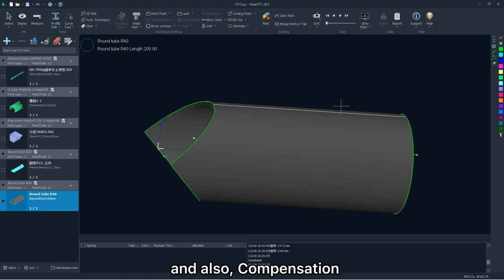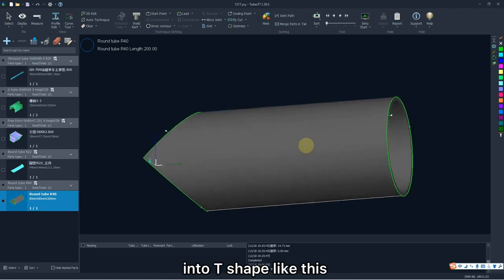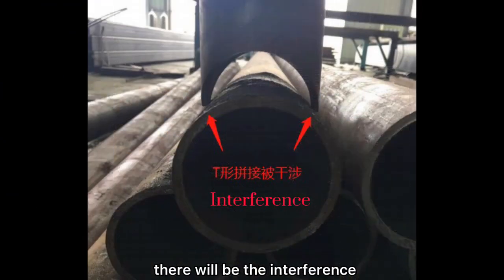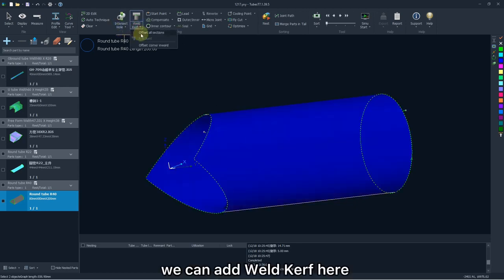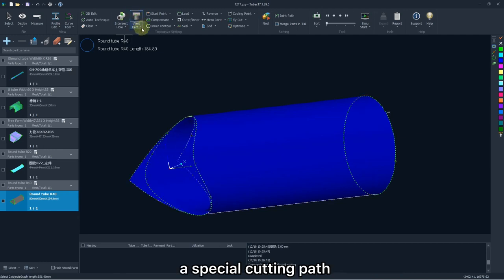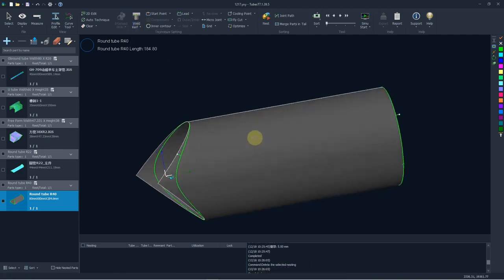And also compensation for special parts to be jointed into a T-shape like this. If you just cut it according to this kind of cutting path, there will be interference due to the differences between the inner and outer control. To solve it, we can add a weld curve here. Then TubesT will automatically generate a special cutting path to offset the interference.